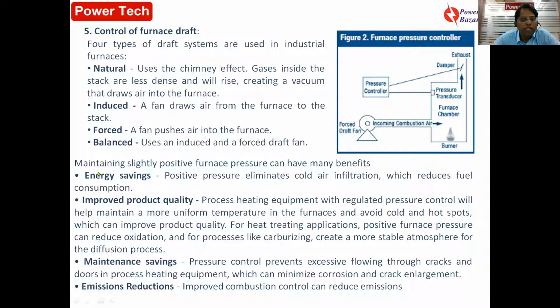Now let us see how by maintaining slightly positive furnace pressure we can have many major benefits. One is energy saving. Positive pressure will eliminate cold air infiltration. That means it will reduce fuel consumption, as the cold air cannot come in. Similarly, there is improved product quality because the cold air is not there. Therefore, a uniform temperature will be achieved, and that will improve the product quality. Similarly, no oxidation will happen, and this will give rise to good quality of product.